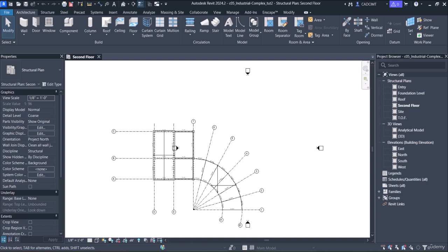Then the next section is copying and pasting the structural elements. In this section, you will select the columns, beams and floor displayed in the second floor structural plan view, copy them to the clipboard and then paste them to the roof level. To do so, ensure that the second floor is selected in the structural plans node. Now press and hold the mouse button and drag the cursor down diagonally and place it in the area bounded by the grid 7 and grid A'.